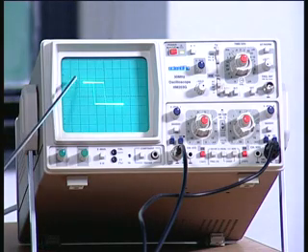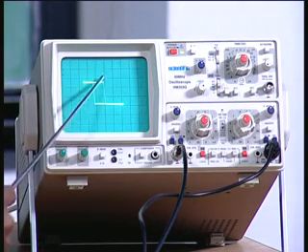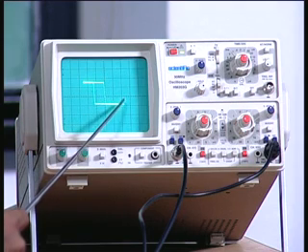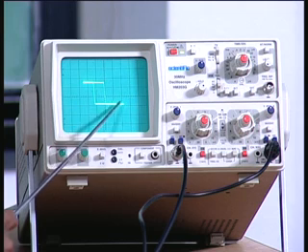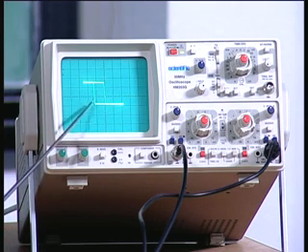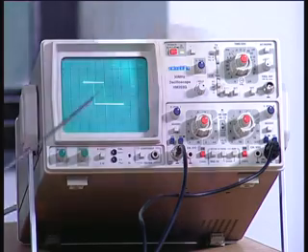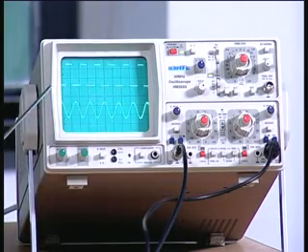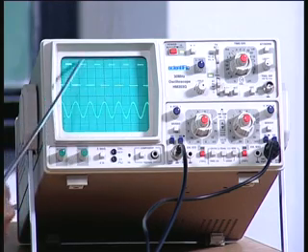So, till it comes to plus VCC there is no transition, and at that time it goes to minus VCC, and after it goes to minus VCC the reference becomes minus beta times VCC, and therefore till it comes here there is no transition and the transition occurs here. So you can very clearly see the transition happening here, and this is the hysteresis graph that you get corresponding to the circuit. When I remove the XY mode, what you see is the normal sine wave as the input and a square wave as the output.